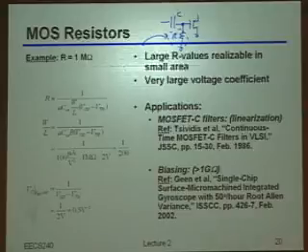Okay, well, actually we'll talk a whole lot more about this later, but basically that resistor there is probably just setting some kind of time constant that, again, has to be low enough, but once it's low enough, you don't really care what it is. Okay? That's probably the most reasonable thing there. There's actually another one, which, if you can read the second line there, is something you might be able to guess at. So where else might you be okay with using this kind of resistor? I should say the second bullet point, to be precise.